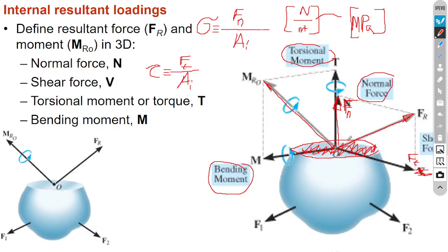But if we substitute the area of the selected cross section while it is under the action of the loading, the area won't be the same as the initial value. It is going to depend on the loading, going to be smaller or in some cases greater.